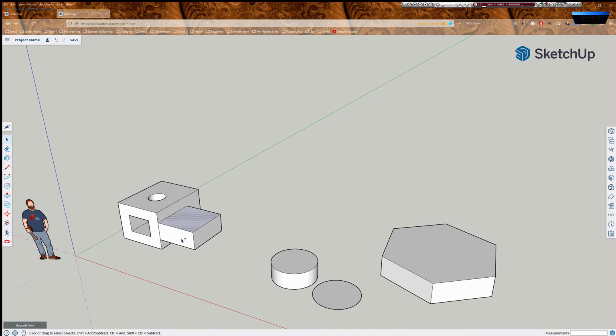So now if I was to manually go through, I can draw a selection box. Let's talk about selection boxes real quick. If I draw a selection box from left to right, you'll see the outline is solid, and you have to completely encompass the object to select it. Okay. So for instance, if I do this here, you'll see that I've only fully selected or encompassed that cylinder. So it didn't select anything here.